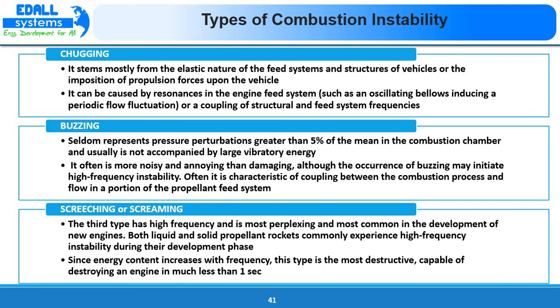So this is the major problem when we are dealing with liquid propellant rocket engines, that a separate propellant feed system is used. So when frequencies of this feed system are interacting with the combustion process or with the structural frequencies, then these instabilities come into the picture. So this buzzing instability is not much damaging, but it is very noisy and very annoying.